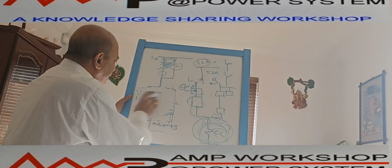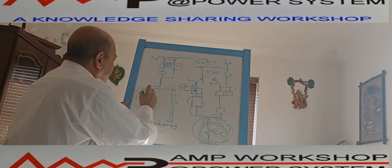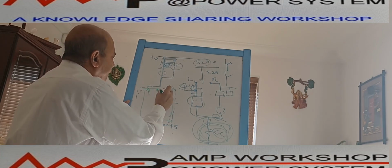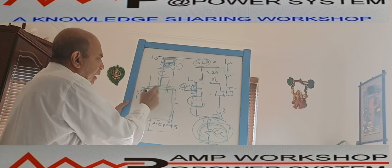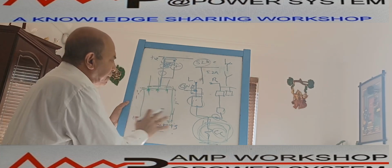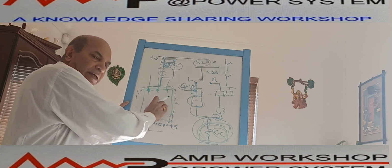But all this anti-pumping device is inside the breaker chamber. If you see the breaker chamber, inside it there is a pin arrangement. Through the pin, these circuits are connected. This pin is coming over here on the back side. It is connected on the back side, and there is a male plug. The male plug is inserted over here, and through the male plug, all these contacts go to the panel wiring circuits. That's why it is inside the breaker chamber. You cannot see this anti-pumping relay outside. It will live inside the breaker chamber.